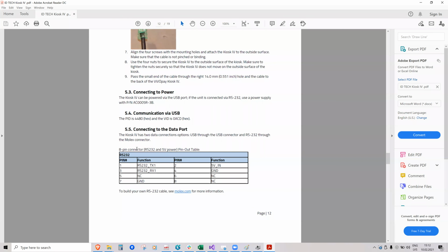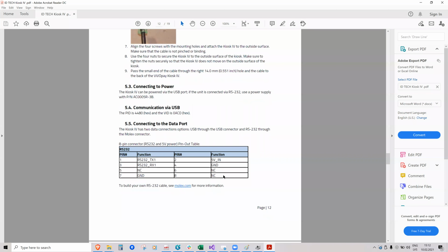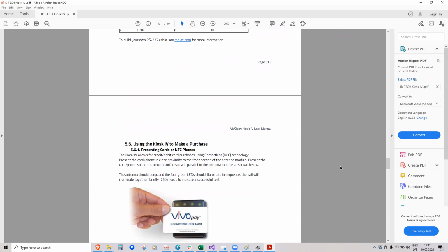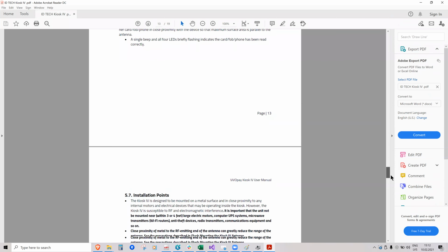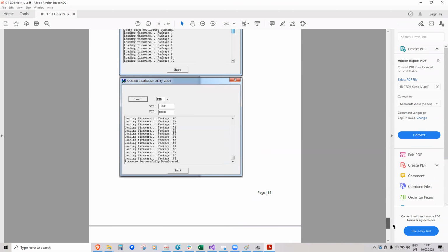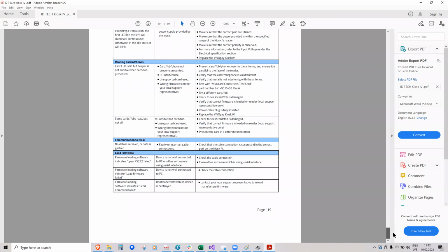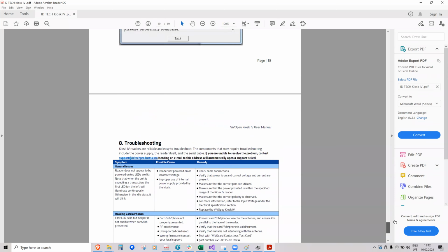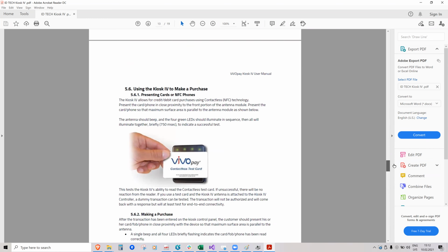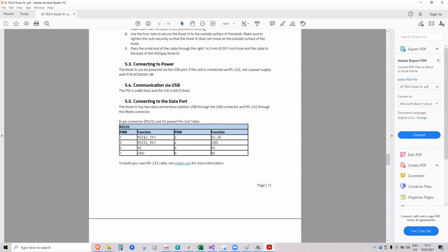You cannot really know it in advance because this device's datasheet doesn't really say the voltage levels on the UART lines. So the only thing that you can do is you have to first buy one and then measure the voltage level of these pins.